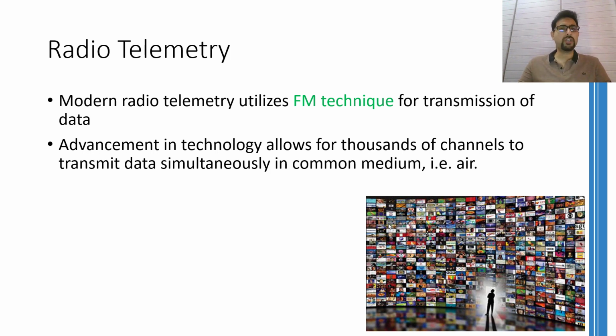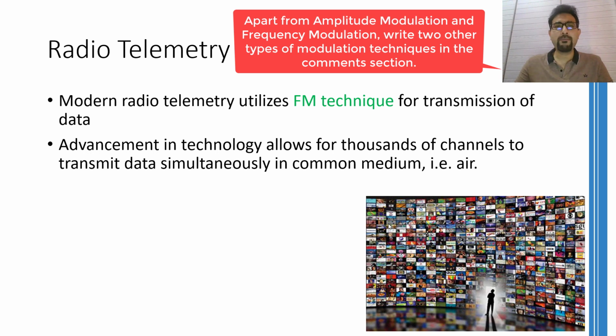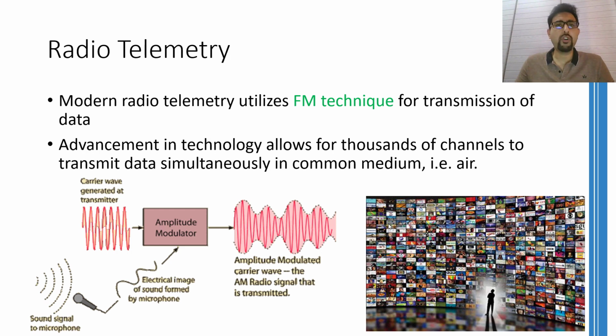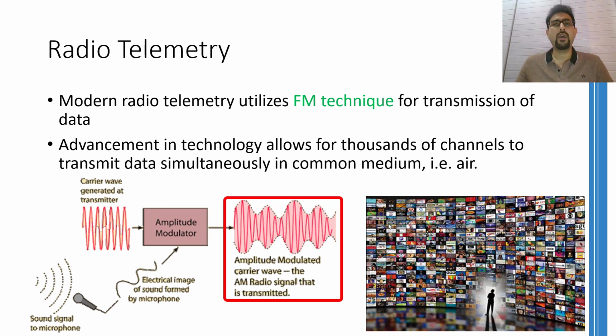The trick in the modulation is to encode the information in some attribute of a high frequency signal. For example, in case of amplitude modulation, the information is hidden in the amplitude of the carrier signal. This carrier signal is normally a high-frequency sinusoid whose amplitude is directly dependent on the modulating signal. The signal that we are trying to transmit from one point to the other point is in fact this modulating signal. The net result of modulating is a carrier signal with modified amplitude. This modified signal is called the modulated signal.